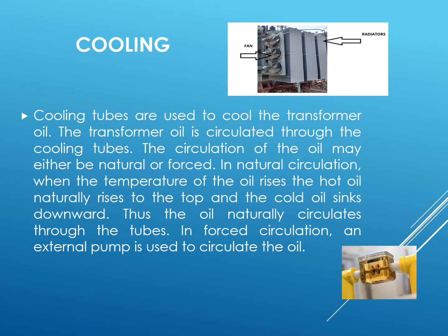Transformer oil is used for the cooling purpose. In addition to that, external radiators are used. The oil circulates around the transformer and moves through the radiators where the heat is released to the surrounding air. Sometimes cooling fans blow air over the radiators to accelerate the cooling process.